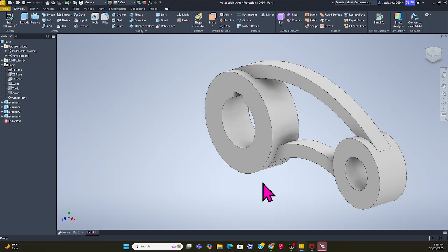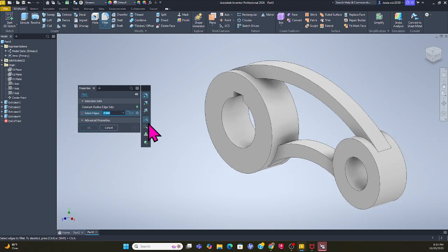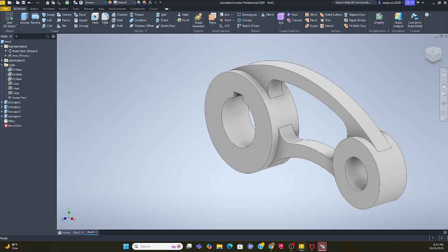The last thing I need to do here will be the fillet, and I'm going to go ahead and fillet with the measurement of 8. I got 4 of those, so that is 1, 2, and there's an edge right here. I need to grab 3. There's one more over there, 4. So those are done. And then I also got this right here to be 2 in radius.